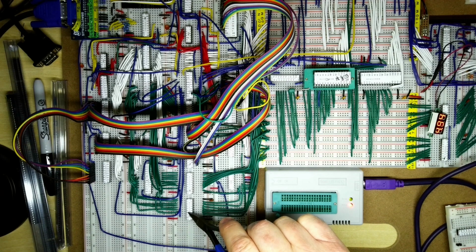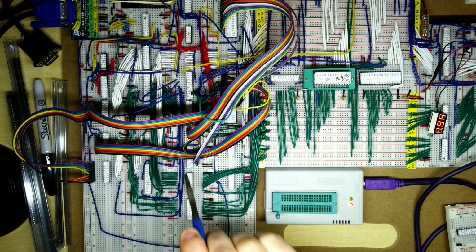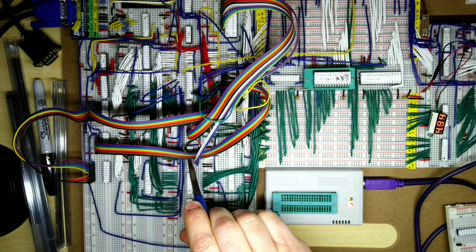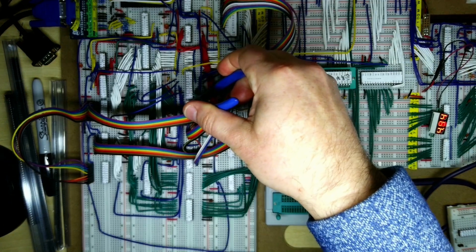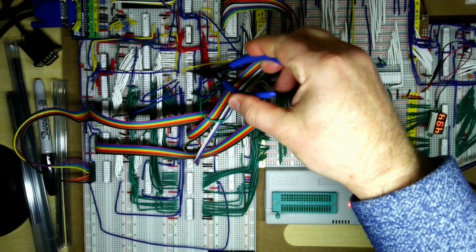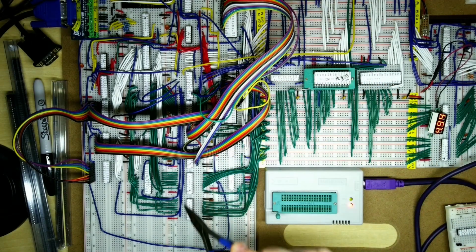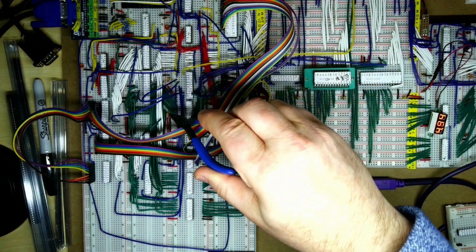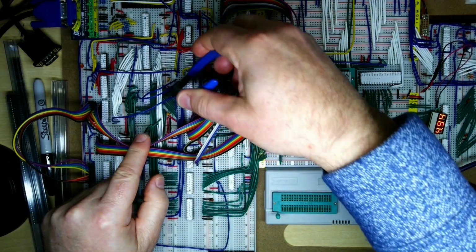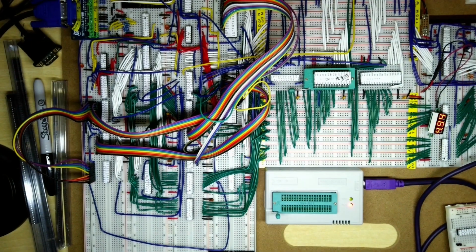The CPU address multiplexers are going to go here, so this is where the two buffers are, and the CRTC2 and CRTC1 are here as well. Now the only issue is, I think it might be a little bit tight to squeeze it in, so I might need to shuffle things around a little bit to fit this one in here. Hopefully I'll be able to put things in so that the existing wires and things, so you see here that the buses are being connected up here, I should be able to do it so that I won't have to move things around too much.